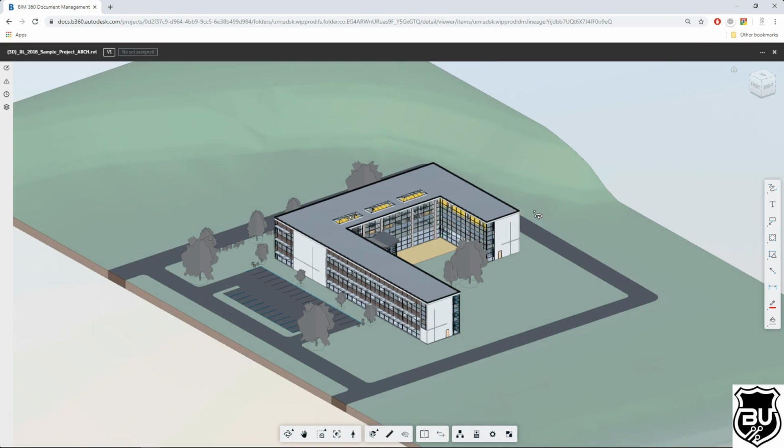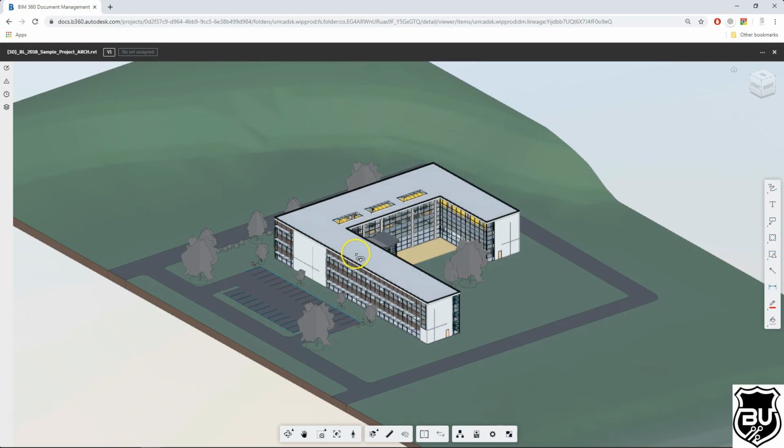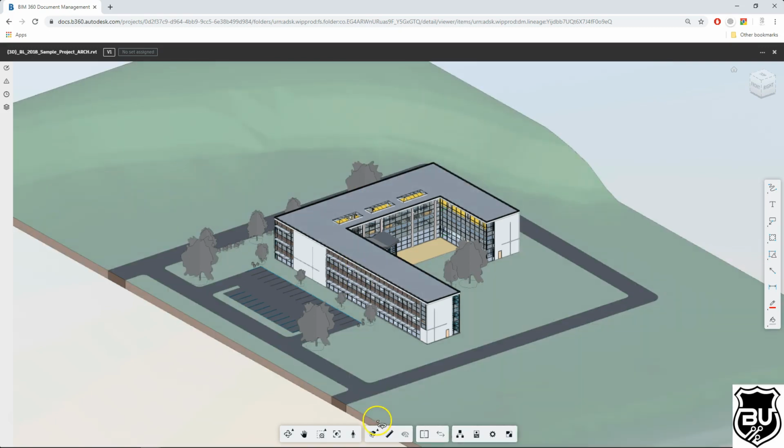And right now you can only see the exterior of the building, so we're going to use the function that's very similar to a Revit section box, so that it enables us to see the interior of the building. That function in Revit is this one over here in BIM 360, section analysis at the bottom. You click on the button. You need to click slightly at the top, otherwise you use the default settings. There's different planes, X plane, Y plane and Z plane. Normally what I like to use is something similar to Revit, which is just a box. So use the fourth option box here.